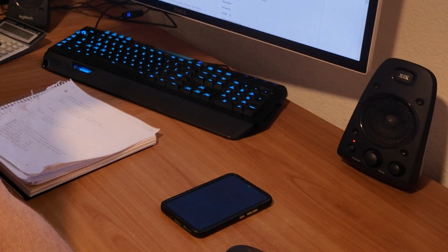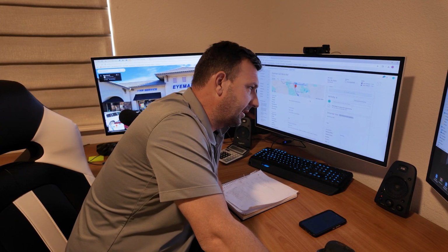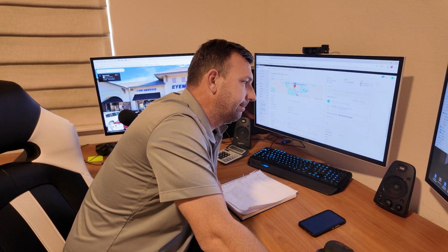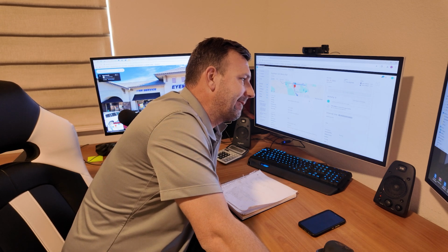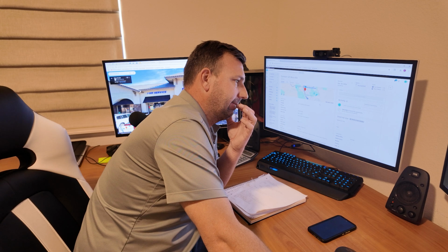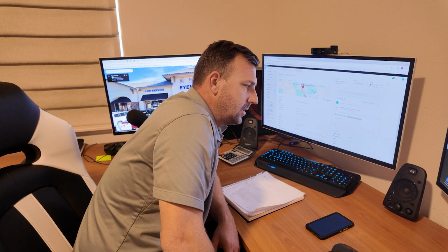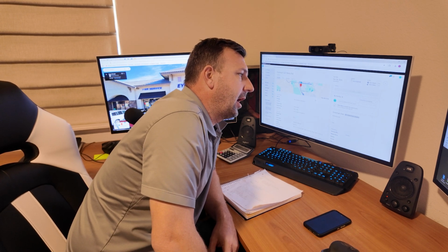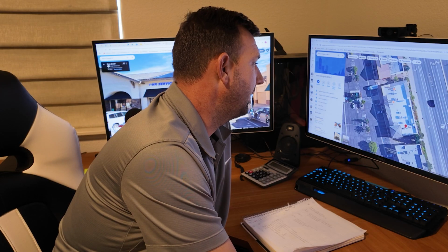Yeah, we can definitely do that. It's a post-tension slab. How do we handle that? Well, you'd have to get it x-rayed. We do not do that, so you'd have to call Tom Mason to x-ray it. Otherwise you'd score it, jackhammer it, and it's a mess. Yeah, but at least that's what the drawings say. I mean, who knows? But I could put the x-ray off on the general. Yeah, I find it extraordinarily odd that it's a post-tension slab. It might not be. That's just what the drawings say. Okay, so it just makes it more complicated.